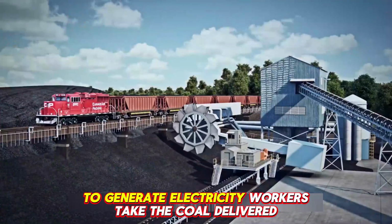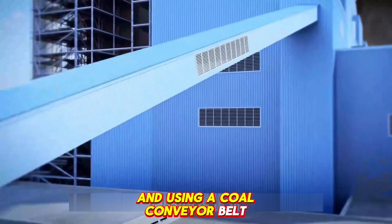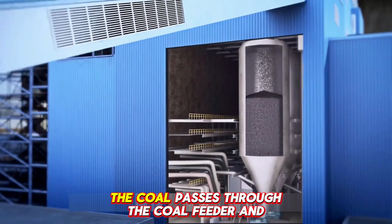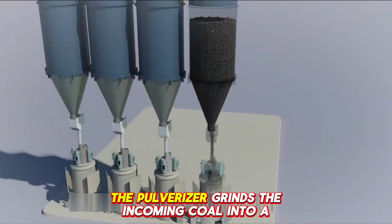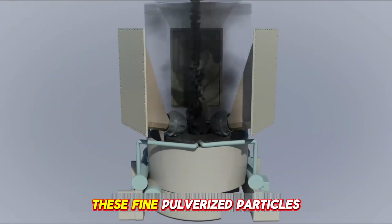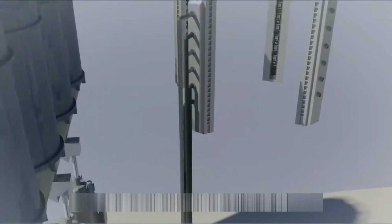To generate electricity, workers take the coal delivered by train and, using a coal conveyor belt, transport it to the power plant's coal feeder. The coal passes through the coal feeder and flows into the pulverizer below. The pulverizer grinds the incoming coal into a powder. These fine, pulverized particles are then carried through an air duct to the burner.